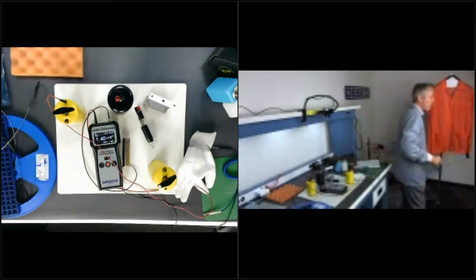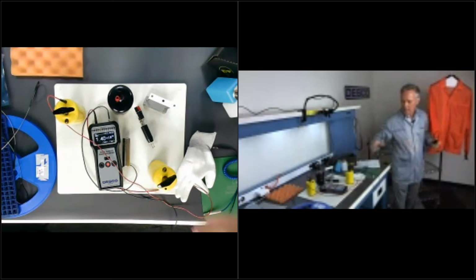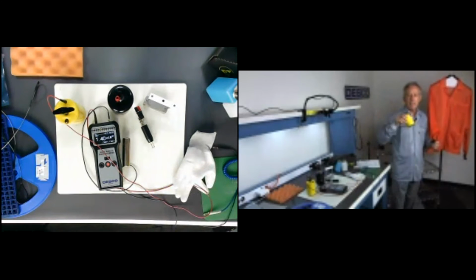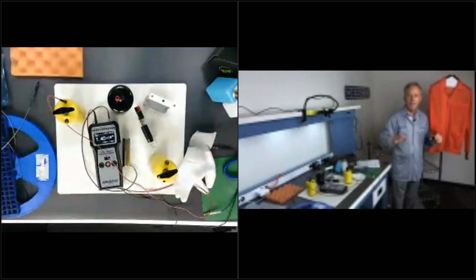So if you were to refer again to TR53, you would see that TR53 has these little clamps here that you attach to your sleeve. One of the reasons they use these is to make sure it's easy to isolate the garment from ground. I could use my 5-pound weights on each sleeve if I want to, but I need to find a place, like a conference table or something, where I can spread that smock out. You don't want to test it on your ESD mat. So this is great because I can just hang my garment up.